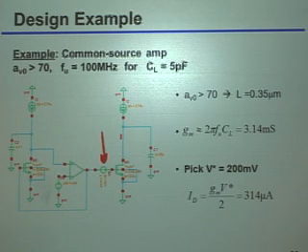Yes? The op-amp that's used there, it has a really high output impedance, right? Oh, actually, this one really is an op-amp, so it has zero output impedance. Then how do you put in the small signal voltage? Because normally you put a capacitor. Oh, so you notice how I put the voltage source in series with the op-amp? That voltage source is just being added to the output of the op-amp. I'm not modulating this whatsoever. I'm just changing this voltage relative to that point.